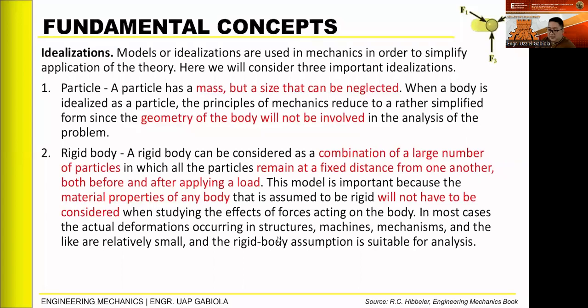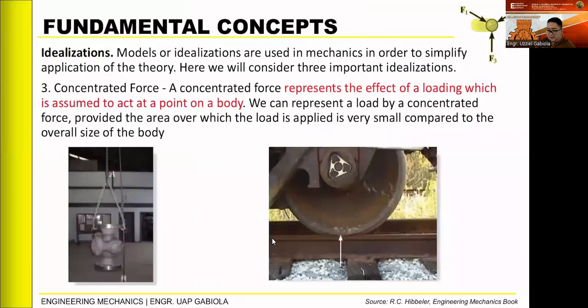Okay? Then last is what we call a concentrated force. Okay? So a concentrated force represents the effect of loading which is assumed to act at a point on a body. Okay? So it is represented by a single point in our system. So we can represent a load by a concentrated force provided that the area over which the load is applied is very small compared to the overall size of the body.